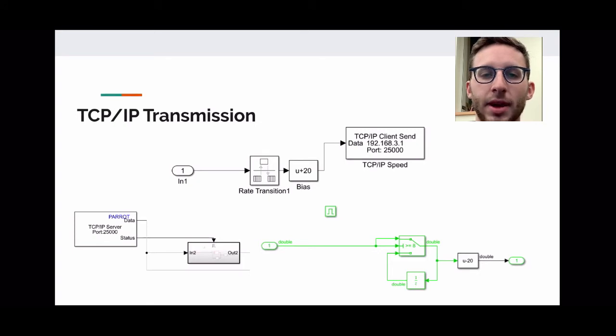In this case, the values were close to 0 but not equal to 0. To fix this, we added a bias of 20, which then amplified all the error. We then filtered out any value less than 8 and then subtracted 20 to reconstruct the signal. This proved to work very well for all types of inputs, including sine waves and square waves.